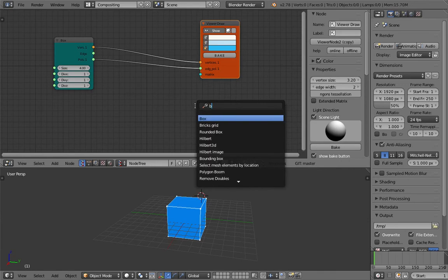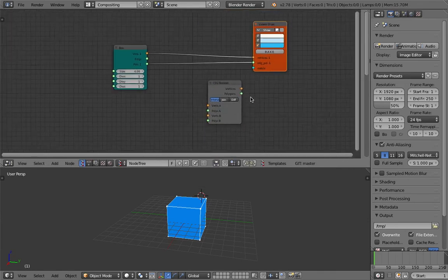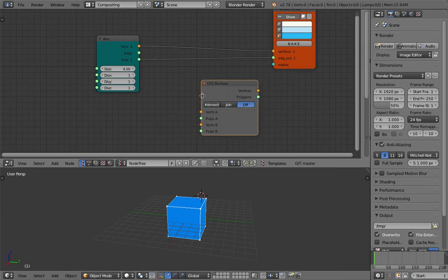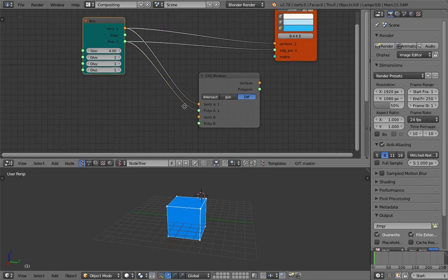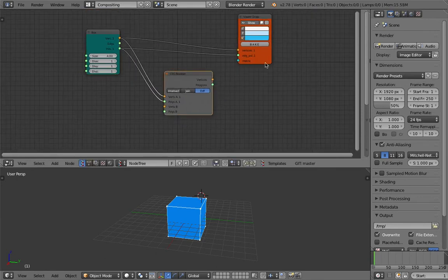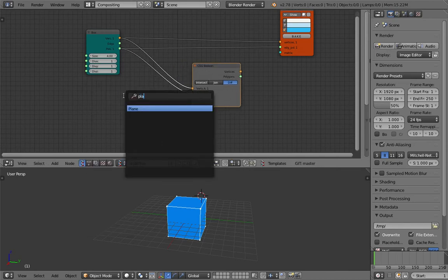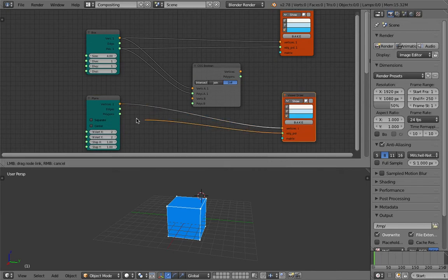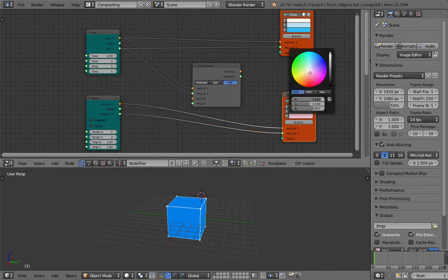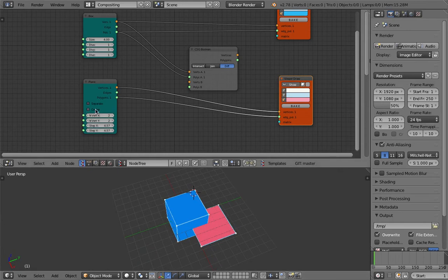And we know that we want to do a Boolean cut. So we set up everything first, and we're gonna do difference. This is gonna be the original box object, and we just need to provide the plane to cut this object. So let's create a plane, and let's fill the plane object. Give it a different color. Okay, that's it. By default, the plane is being generated like that.